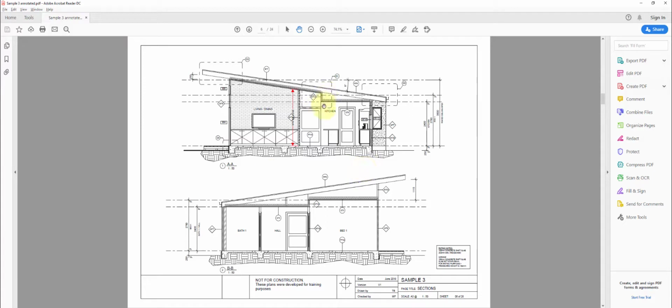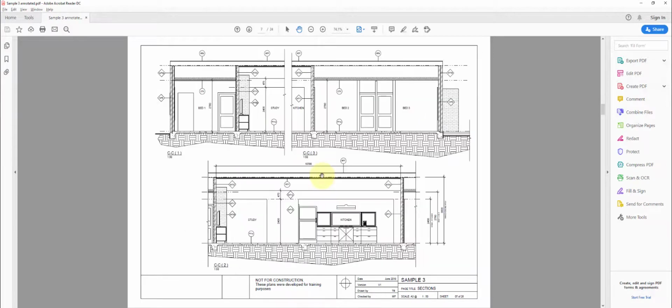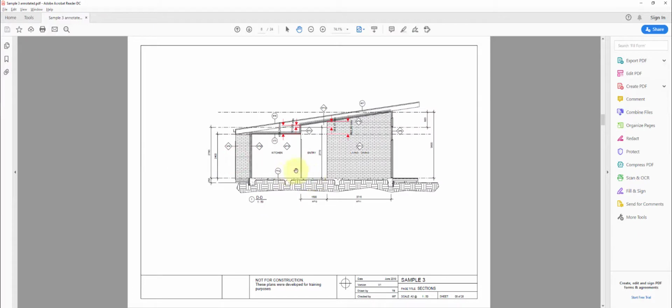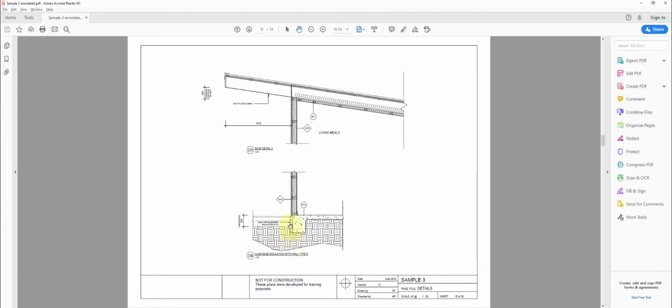You can see this drop-down ceiling section in the kitchen for the bulkhead, as well as some of these indications that we're going to need to start modelling some of these floating walls that are adjacent to the roof space. Here we see that internal wall type in the kitchen, living, dining area, open plan space, and it's adjacent to roof space portion as well, and some further dimensions here that we'll need when we start adding those floating walls. You can see here we've got some slab edge insulation on our slab, it looks like.